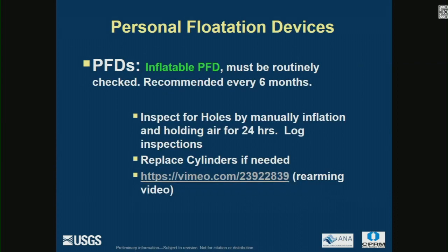So we have these inflatable PFDs now that are out. They're much lightweight. They're cooler in the summer, but we have to do the maintenance on those, and they have to be inspected routinely to make sure that they're still able to work. How many folks have seen these type of life jackets where they have the CO2 cartridges and they inflate? Right. So the thing that you have to do with those is keep the maintenance up on them. I had one myself that I thought was fine. Went to do an inspection on it and blow it up. It would not hold air for more than 5 minutes. The seam had a crack in the side of it.